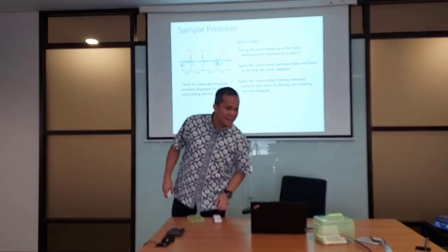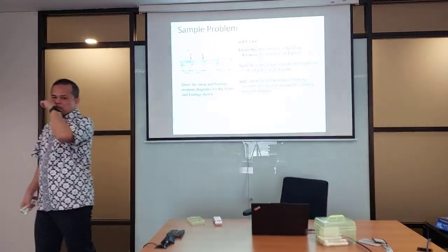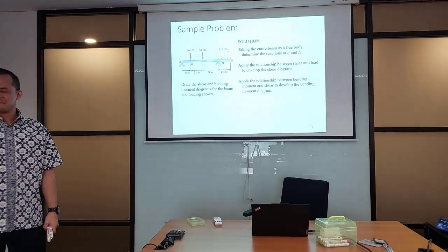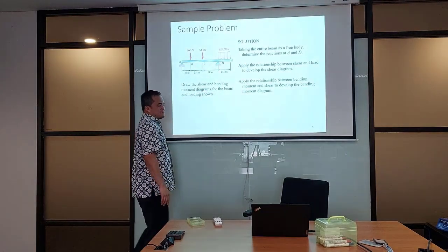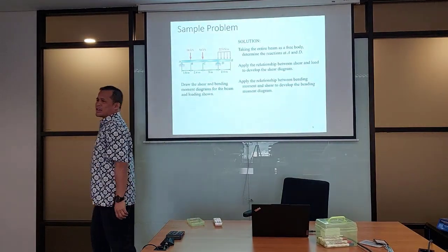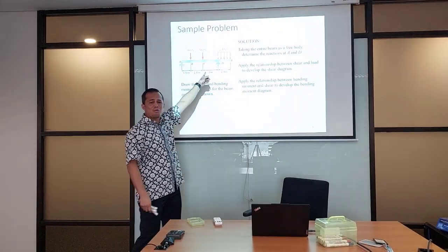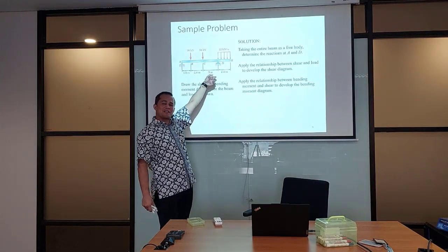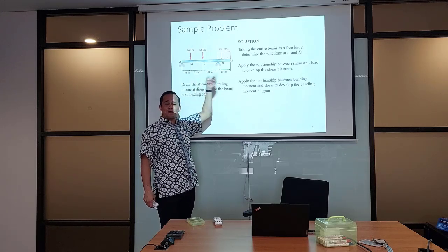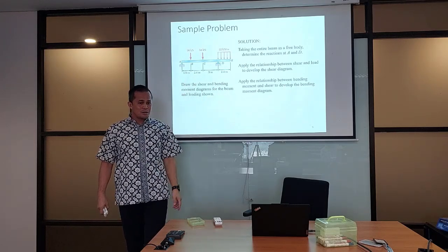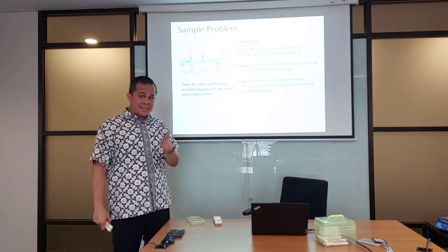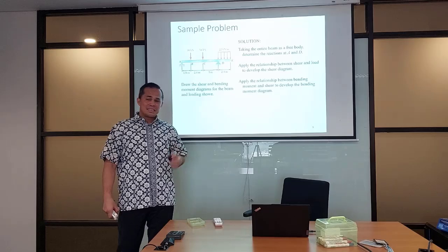Okay, let's go with this now. The beam has 3 applied forces of 90, 40, and 54 kilonewton, and a distributed one. And you may get tricked with this. The 20 kilonewton per meter is the applied load. That's the gradient and the constant of the applied load.